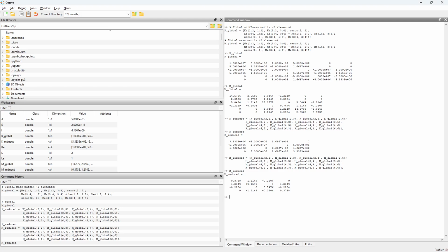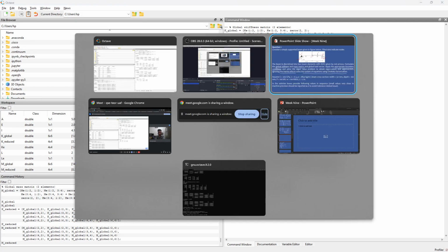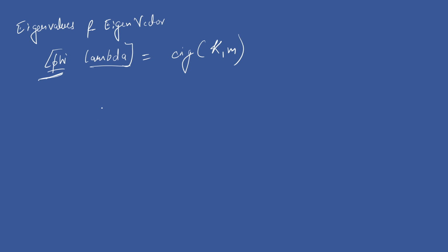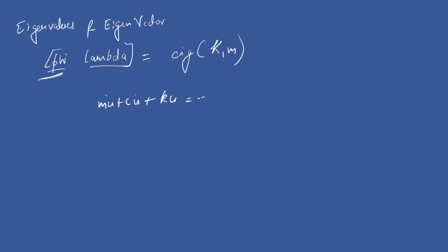So we are having the stiffness matrix and mass matrix. So you know your equation of motion looks like m u double dot plus c u dot plus k u is your forcing function minus dt. So here you are basically neglecting the inertial effects, so this term will become 0.